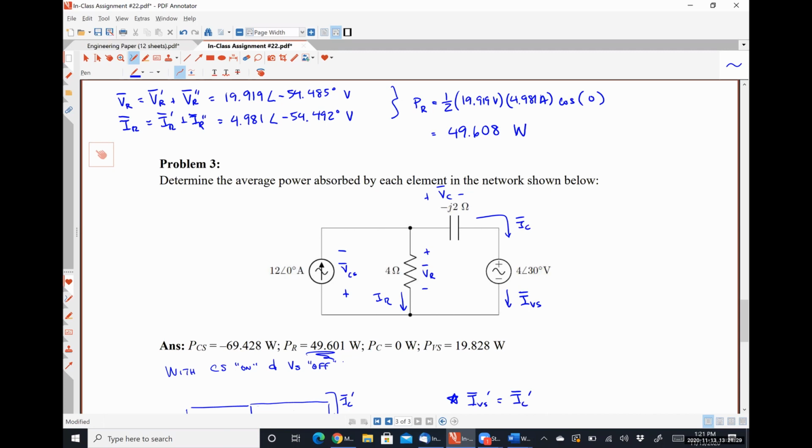You know what, now that I'm looking at it and you mention it, the question there is, could we have solved this thing using Kirchhoff's current law? If we considered, let me put a different color here, put that guy as ground and call this guy Vx, that's the only unknown voltage. So we could have avoided using superposition, but I didn't notice it. So yeah, you're 100% right.